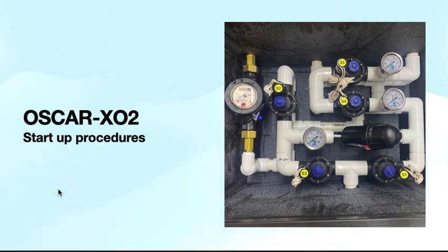If you don't do this and you have problems, this is the first thing you should do, these next few steps that we're talking about with the startup procedures. So you can see here, there's 4 connections that you'll make. This is the inside of that reverse flush headworks. That headworks that's on top of the tank that has the pump going out to the Oscar, going out to the drain field. And so the inside, everything on the inside here is already made for you. This is how it will show up on site.